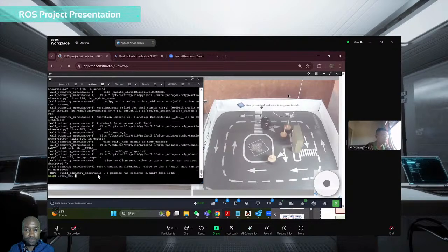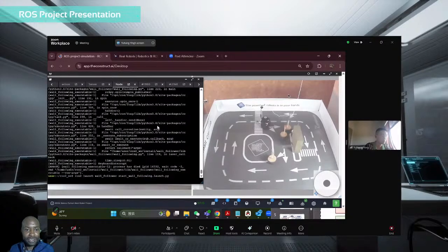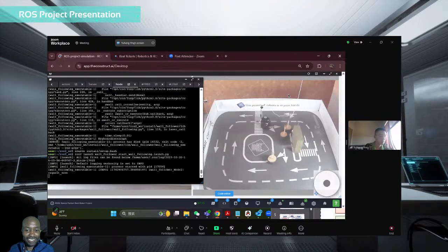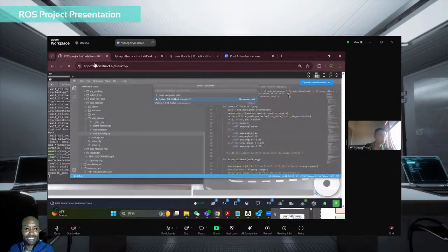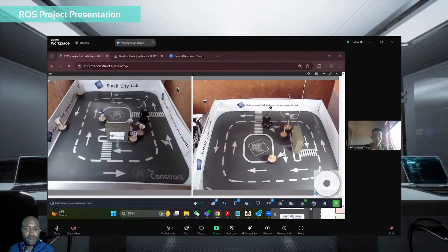I prefer to start them separately. Although we can start all, if we start all, the information will be mixed, and it's hard to see what's going on. I see. Normally, let's say your service, after it has found the wall, must now hand over control to the wall follower, and then the wall follower must also hand over control to the odometry. If you do that right, you don't have problems having to start everything in one launch file. Yes. All right, let's see how it goes now.